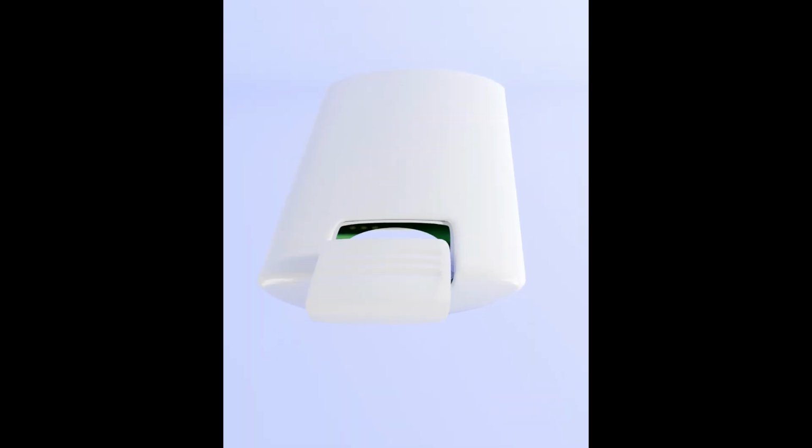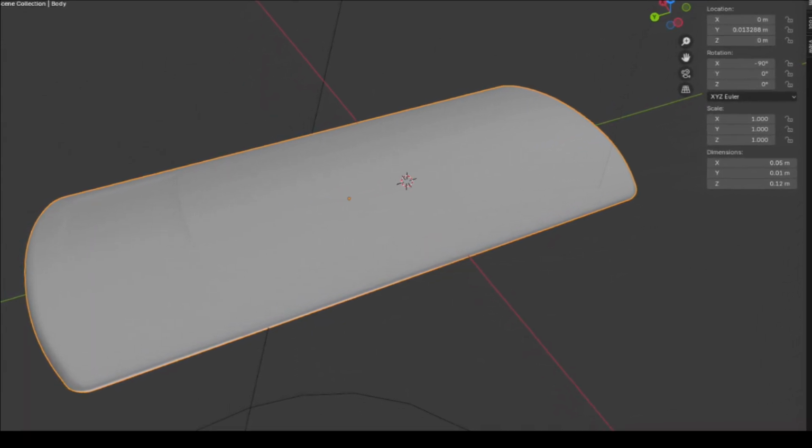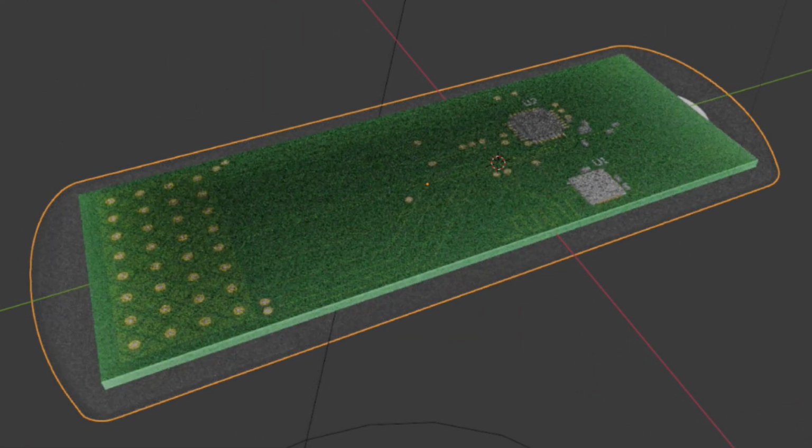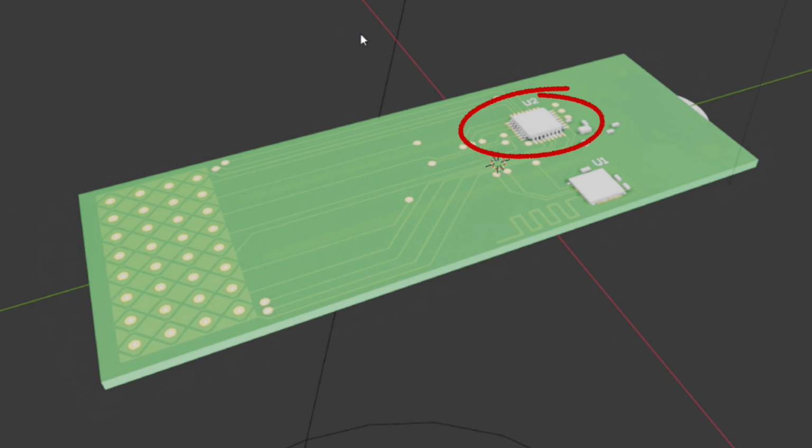The design example we will be using is a Bluetooth remote controller. The application is powered from a CR2032 battery, and it uses a Microchip ATSAMD21E MCU for touch and a Nordic NRF52832 SoC for Bluetooth low-energy communication.